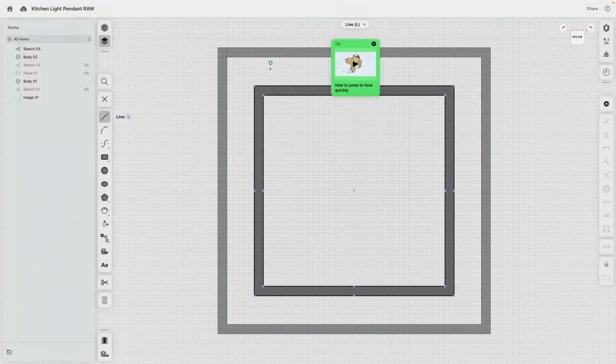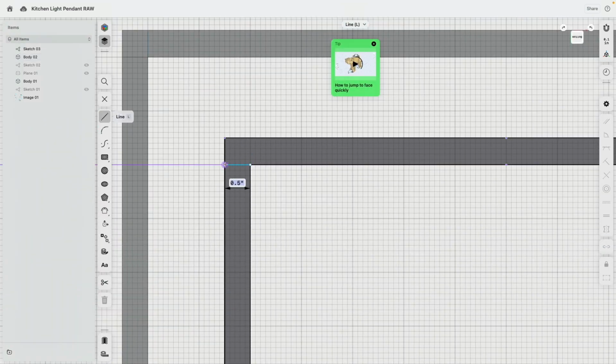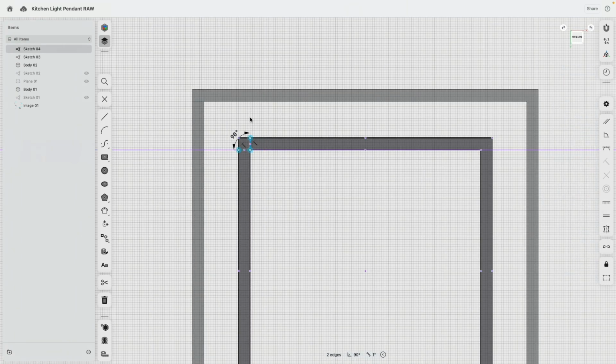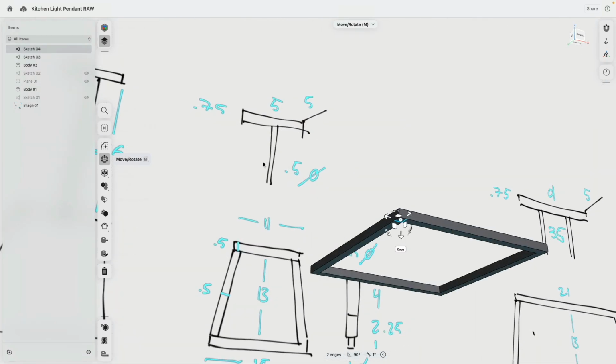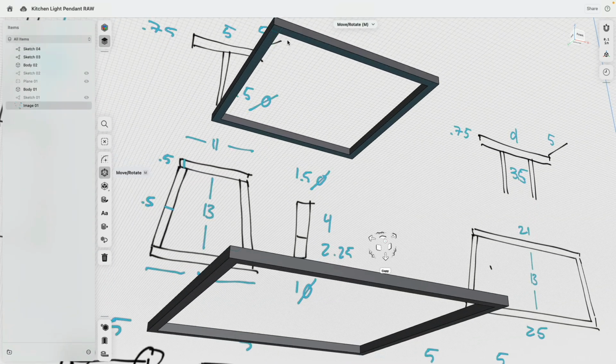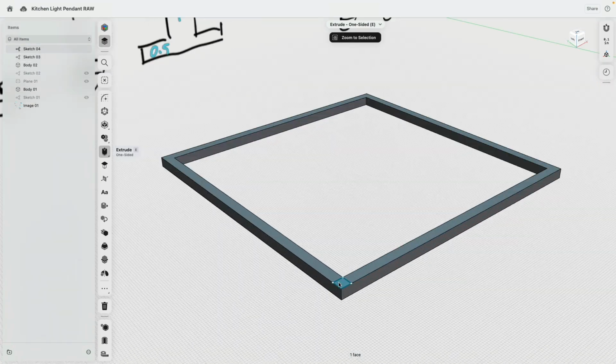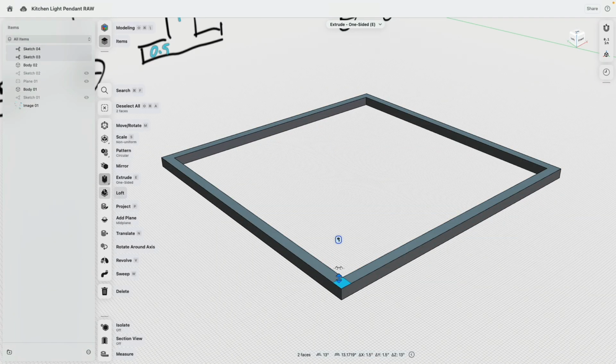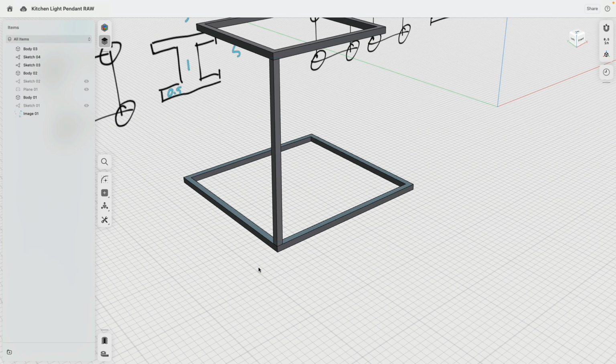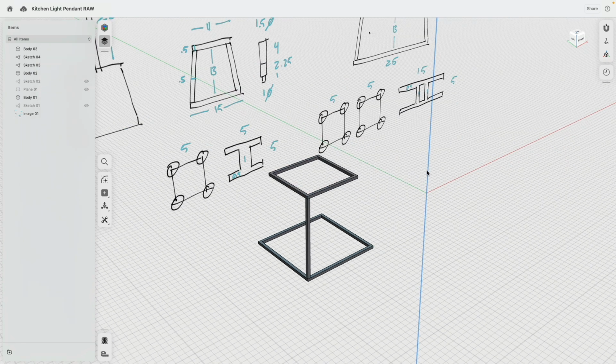Select the face, sketch, click and click, escape, select the edges, horizontal, vertical, escape that sketch environment, select the sketch profile, same here, and then we do a loft.